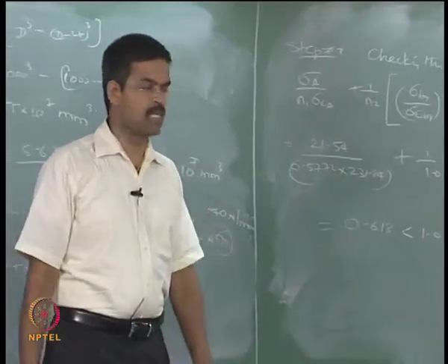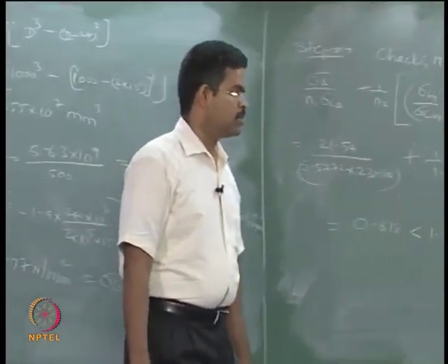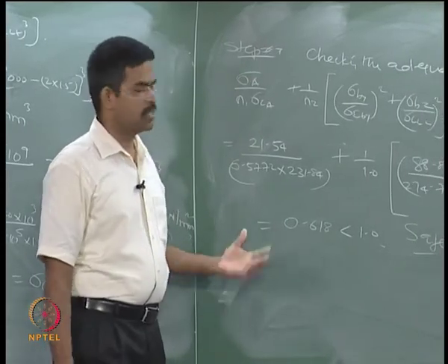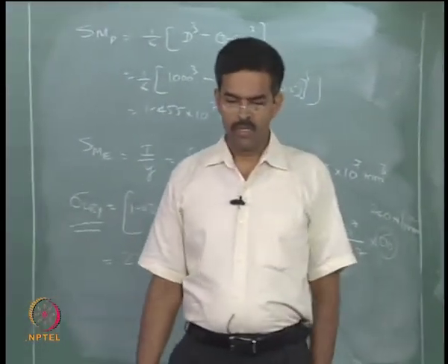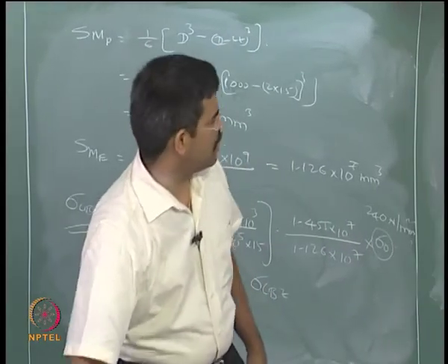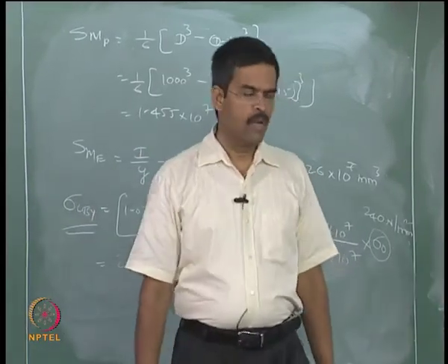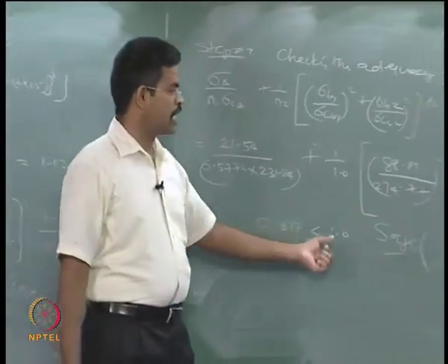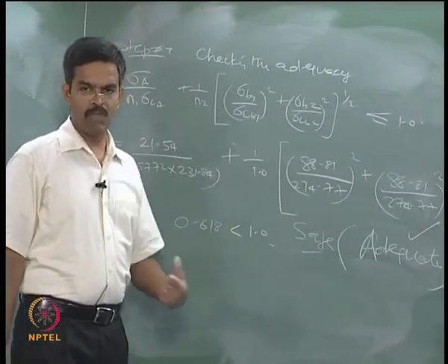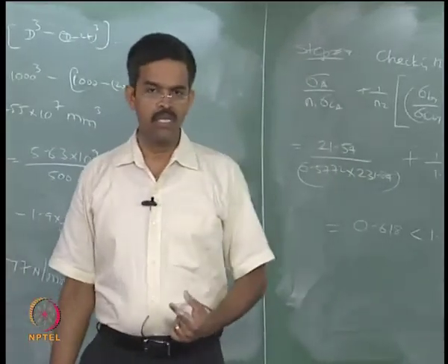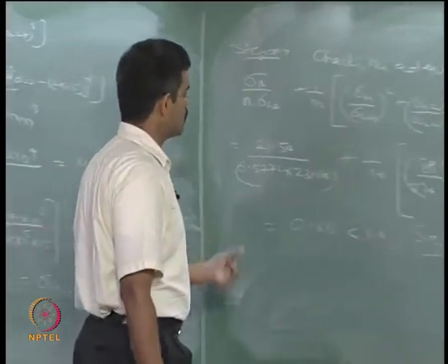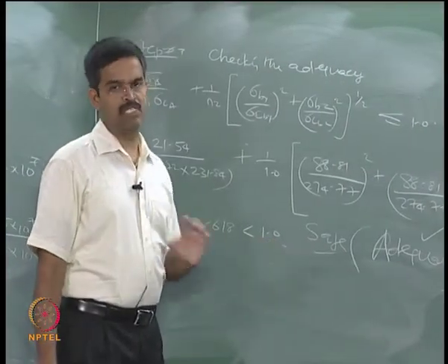So one can check the design for a combined action of compressive force and bending, or pure axial compression, with the help of these two examples, in which the equations have been derived and used from the international codes. These two lectures, the last one and the current one, will help you look at the uncertainties in the adequacy checking process of the given design. We must certainly understand that in offshore structures the design is not done from scratch; only the adequacy of the assumed dimensions of the members is checked.